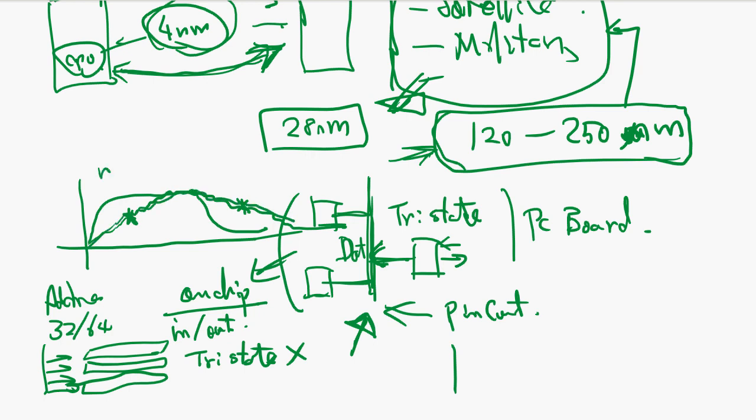This rise time, fall time, you can't have this kind of very prolonged slow signal, because it causes a lot of problems. Here the amplifier gain is highest, and all kinds of bad things happen. It's almost unpredictable what happens, depending on what kind of wire is crossing around this amplifier.